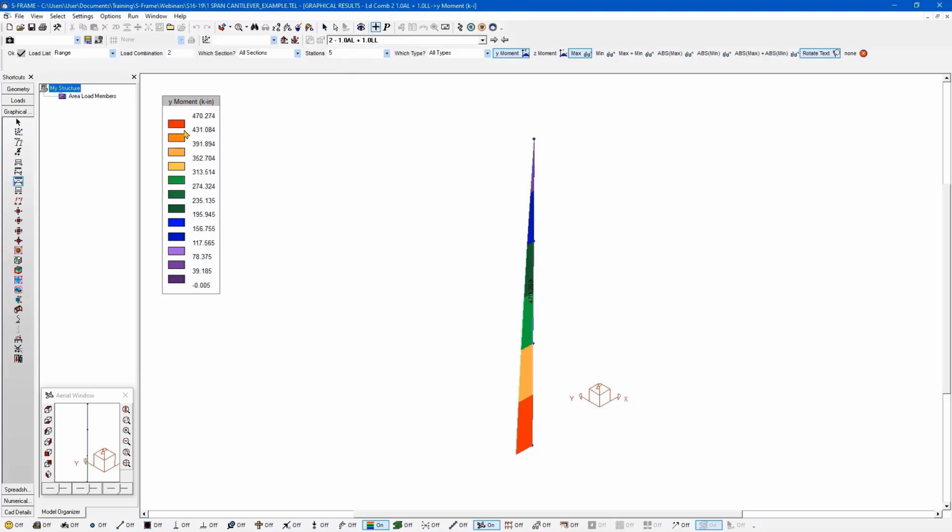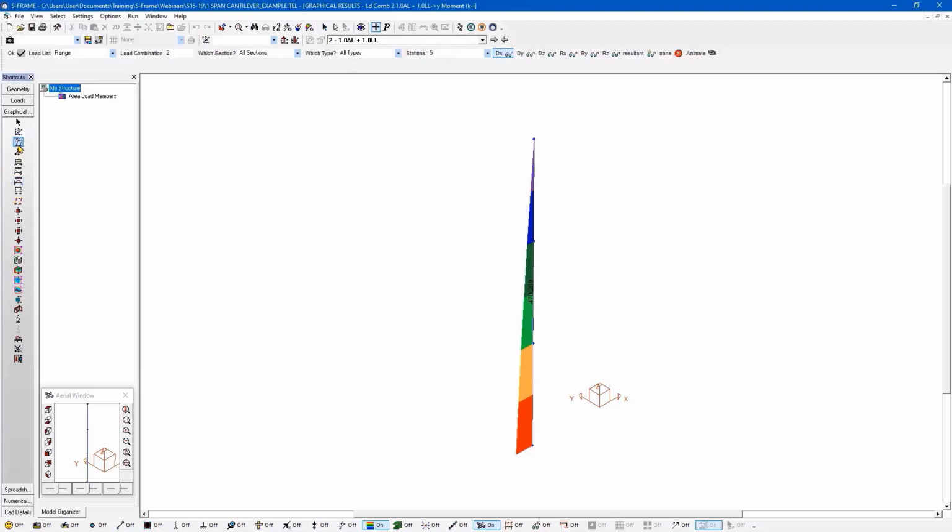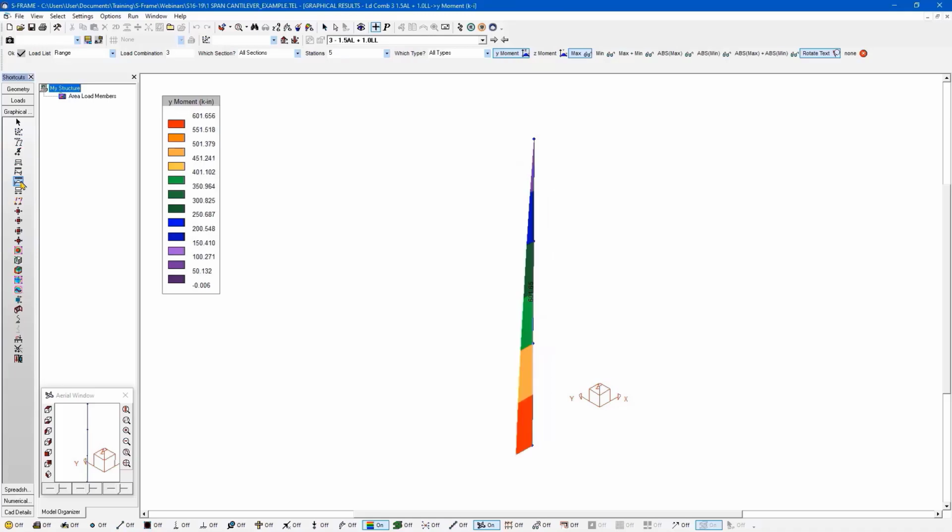So it's increased our moment quite significantly. And we're getting about 0.4 inches more deflection when we include the effects of that axial load, because it is stressing that column, putting it under compression, but we're also having that moment arm developing due to the lateral displacement. Moving it one step up, we get even more deflection, and not surprisingly, even more moments.